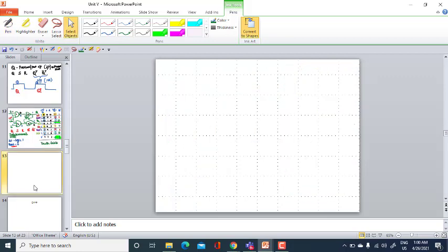While discussing the flip-flop, we should also consider one more table, namely the excitation table. This will be helpful while designing your sequential circuit. With the knowledge of the present state and the next state, we can determine what is the input.